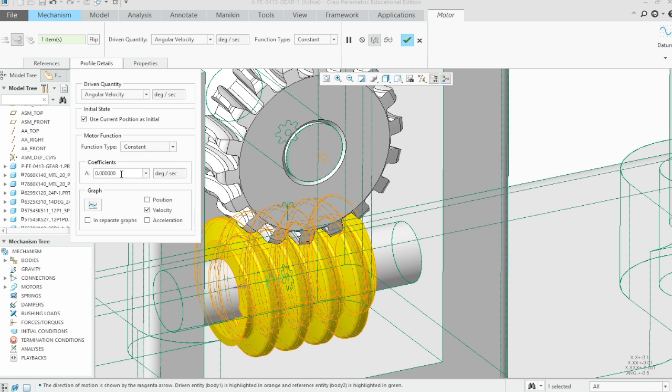Off this one, we'll just go constant, and these are degrees per second. So if you were to count in your mind for your design, for your hand design, you were to say 1001, how much would you want this thing to rotate around? So if we go at, let's say, 360 degrees per second, so 1001, and then if we run a video for 10 seconds, that means it's only going to turn like 10 times. So let's move this thing up and let's try 700 degrees per second, which seems kind of fast, but not too fast in the real world design.